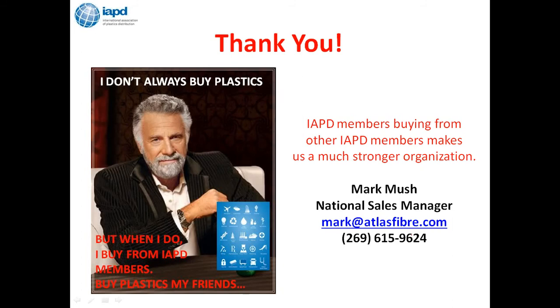G5 has kind of fallen by the wayside because all of the properties are exceeded by the G9. They're both glass melamine grades, but the G9 characteristics pretty much cover all the G5. So G5, you're probably not going to find on anyone's shelf at this point, but if you have to have it, yes, it can still be made.